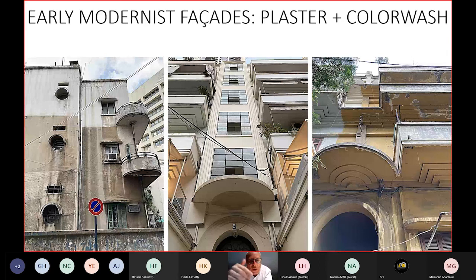that show how they also used the concrete in its most efficient way. So they did not use more, because more at the time was a lot of money. They really cast the concrete in the most efficient way to have the thinnest slab possible at the edge. We have to note here that the slabs were all made out of solid slab, probably between 12 and 15 centimeters thick, with one layer of steel. So really very, very light slabs, practically, compared to what we are building today.